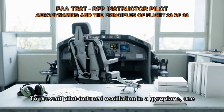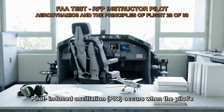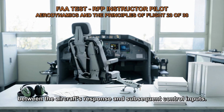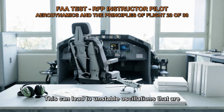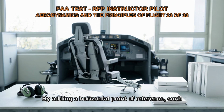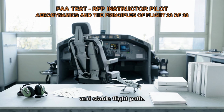To prevent pilot-induced oscillation in a gyroplane, one effective measure is to add a horizontal point of reference. Pilot-induced oscillation, PIO, occurs when the pilot's control inputs inadvertently result in a feedback loop between the aircraft's response and subsequent control inputs. This can lead to unstable oscillations that are difficult to dampen or control. By adding a horizontal point of reference, such as a visible line or instrument, the pilot gains a visual cue for maintaining a steady and stable flight path.